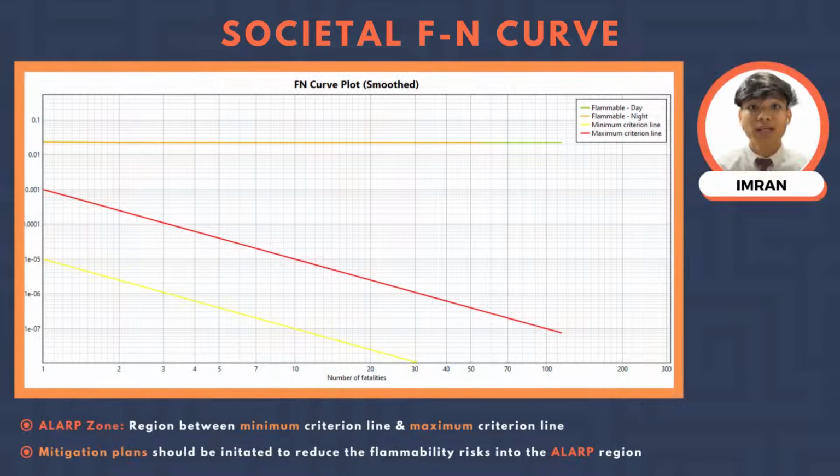Moving on to the FN curve, it can be seen from the figure that both the maximum and minimum criterion lines exhibit an inversely proportional relationship with the number of fatalities. In addition, it is also observed that the flammable risk line of this process plant has propagated over the maximum criterion line, meaning that it has exceeded the acceptable region. Therefore, it is crucial to implement mitigation methods to ensure that the flammable risk can be reduced to the acceptable level, which guarantees the safety of the factory workers as well as the residents in that area.